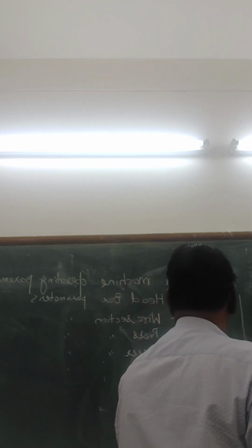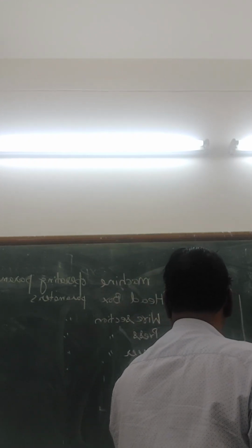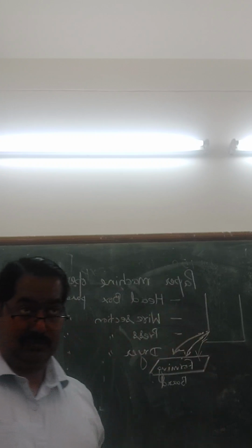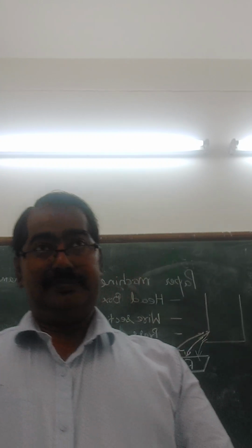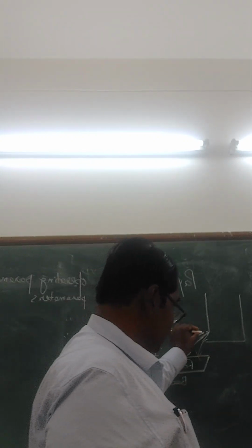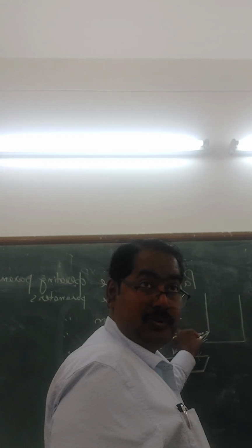This section is called the forming board in the paper machine. So basically the angle will be changed. The angle at which the jet strikes the screen or wire will change with the change of the angle of the upper lip.